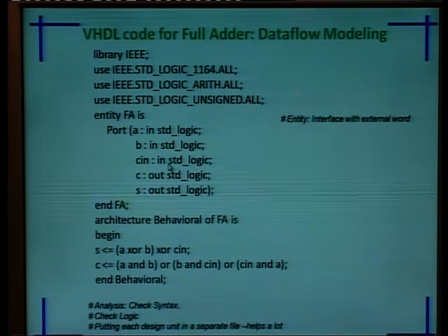Either our check syntax is okay, and that is the direct icon available in the Xilinx software. Once we click on check syntax, if there is any problem or error, a message will be displayed and we have to go to that line to correct it. Then check logic, whether our logic function is okay or not.